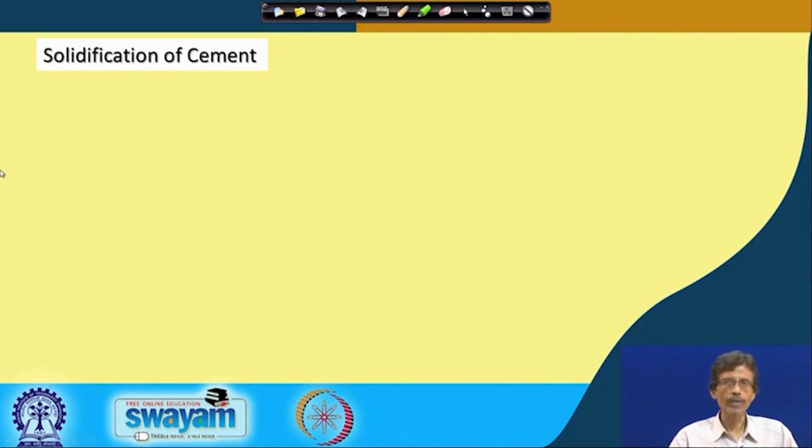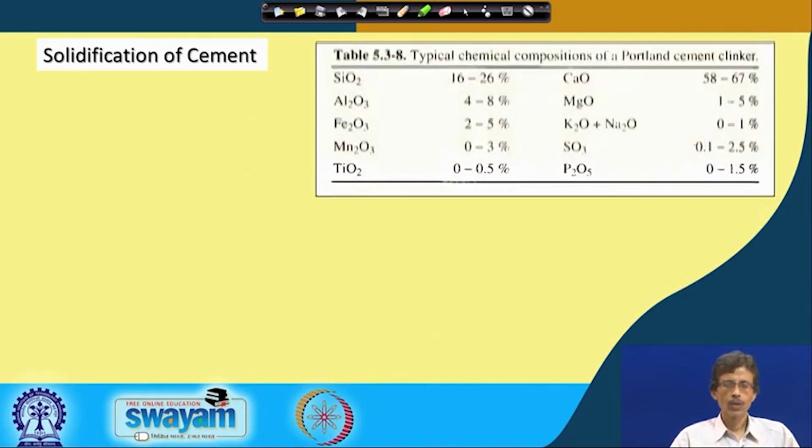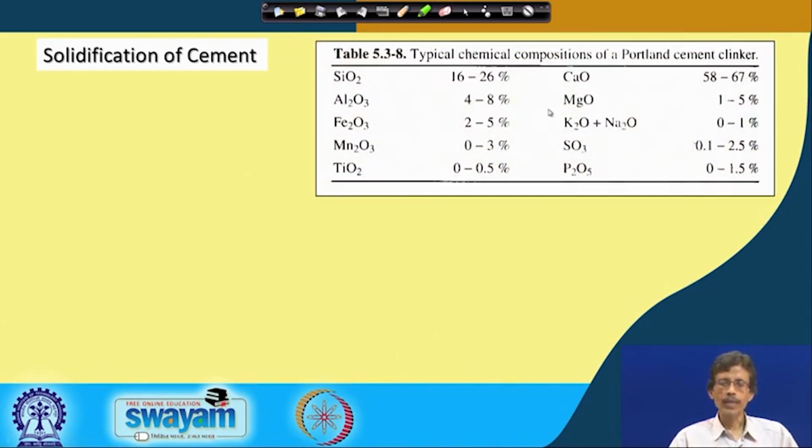But this particular material, which is formed at a very high temperature, will definitely be hygroscopic in nature, and can trap and attract moisture. So, if you put water, it will definitely react with water, and the process is quickly termed the hydration reaction. So, let us consider the different compositions that can be achieved: tricalcium silicate, dicalcium silicate, tricalcium aluminate and the calcium aluminoferrate.